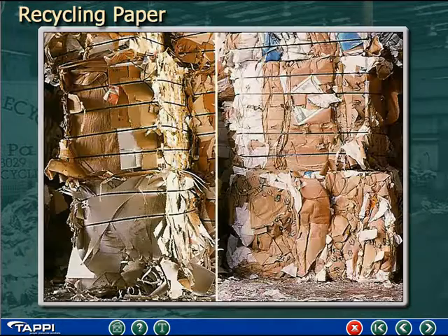So step 1 in the recycling process is to inspect and sort the incoming bales of recycled paper for quality. Remember, the cleaner the incoming waste paper, the easier it is to recycle it into clean new paper. Really bad bales can be rejected, and other bales can be separated based on the suspected level of contaminants. Then the cleanest bales can be mixed with more contaminated ones to keep the level of contaminants under control.